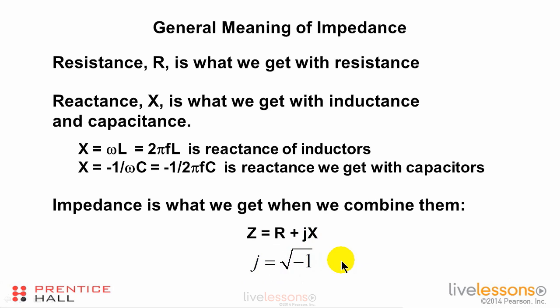There is a point in Electrical Engineering 101 when an instructor or a professor goes through a derivation and he ends up at this point and says that the impedance is resistance plus this times the square root of minus 1. And then typically there's this pregnant pause where the instructor stops and waits for that to sink in, because for many students that's the first time they ever see the expression the square root of minus 1, which we call an imaginary number because the square root of minus 1 does not exist. There is no number that you can multiply by itself and get minus 1.